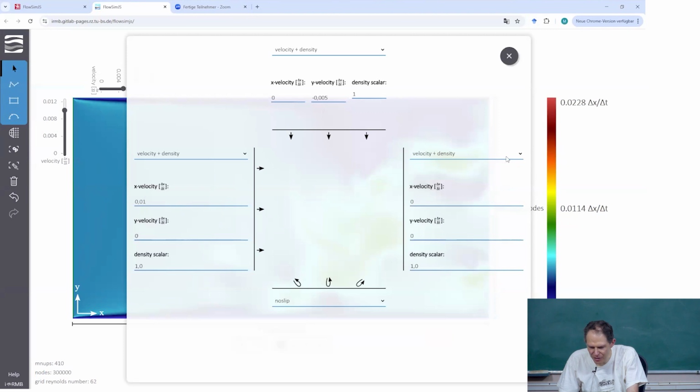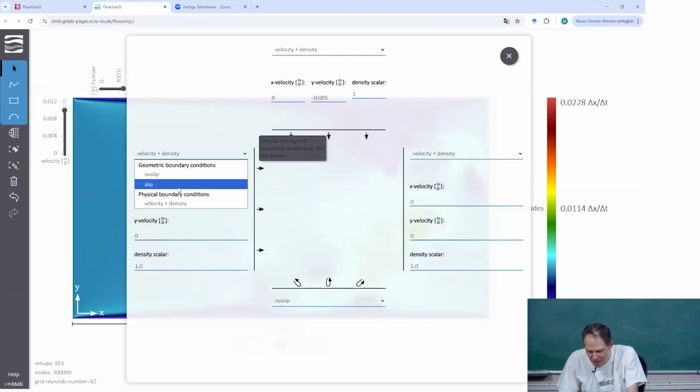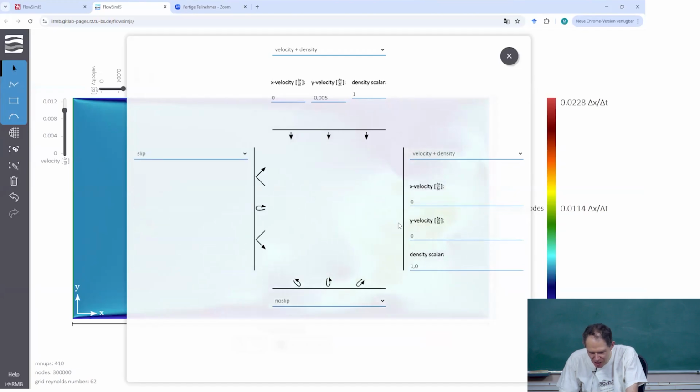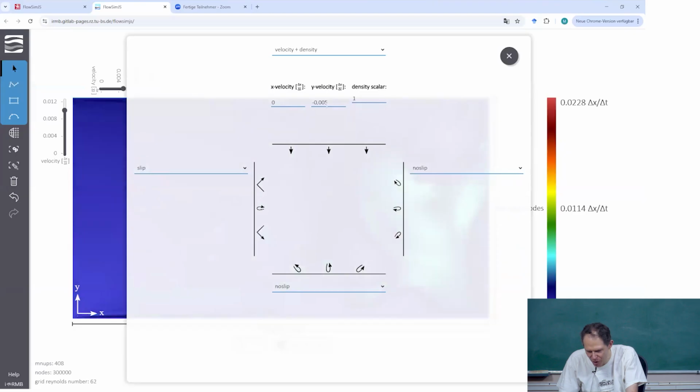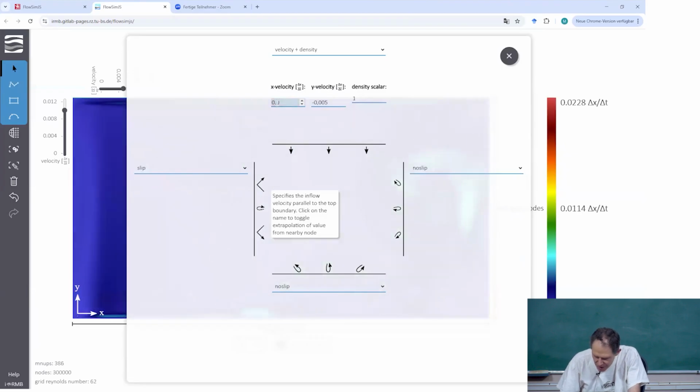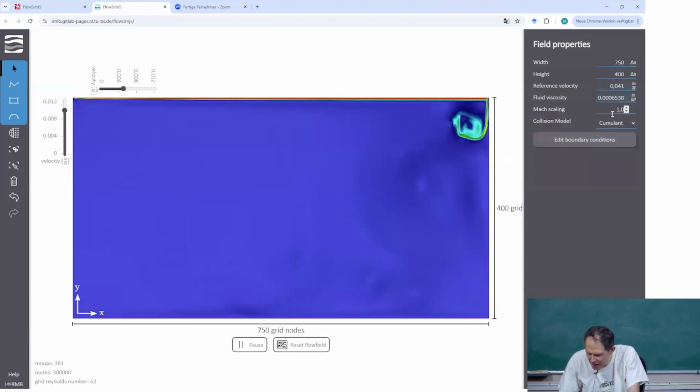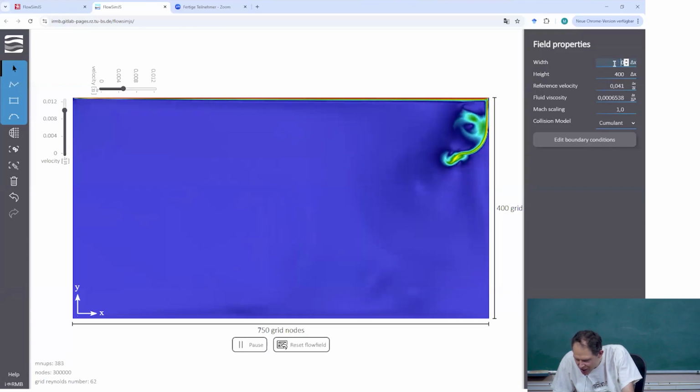So, for example, if you want to do the thing that everybody apparently does first, let's just do this. We can build a lid-driven cavity simulation by putting a no-slip wall boundary condition here, and a no-slip here. So we have no-slip, no-slip, no-slip. And up here, we would have to have the horizontal velocity. Say we put the horizontal velocity to 0.1. Then we potentially want to have this more symmetric, so let's put this to 400. Let's do both 200.